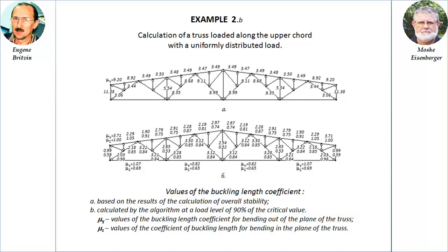Experiments show that the time required to calculate the buckling lengths of all structural elements is comparable to the time required for a single static analysis per one load case. Furthermore, the use of only the band structure of the flexibility matrix does not impose excessive demands on external memory.